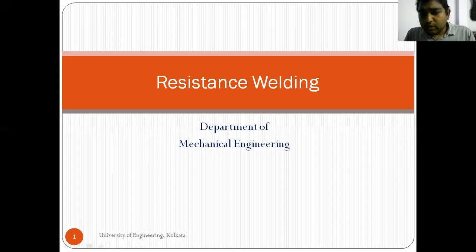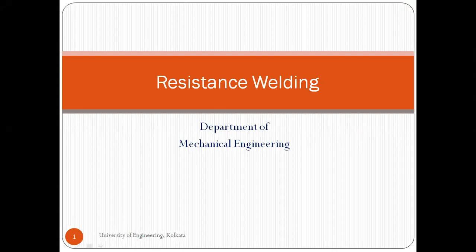So now, the resistance welding process is a process wherein the heat is generated due to resistance heating. There is H equals I square RT, and the resistance is offered by the workpiece material. The maximum thickness that can be welded is up to 12 mm. Mostly in the resistance welding process, sheets are welded. We cannot weld plates as in your manual metal arc welding process, right?